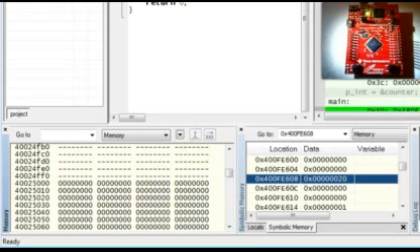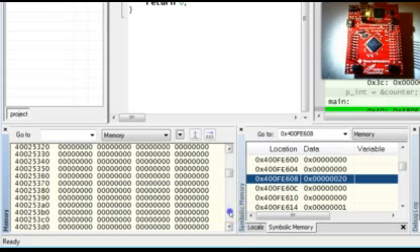As you should read in the GPIO section of the datasheet, you still need to configure the GPIO F bits 1, 2 and 3, which drive red, blue and green colors respectively, as digital outputs. To set the pin's direction as output, scroll down within the GPIO F address block to the address hex 40025400 and set the bits 1, 2 and 3 to 1, which corresponds to 1110 in binary and E in hex.